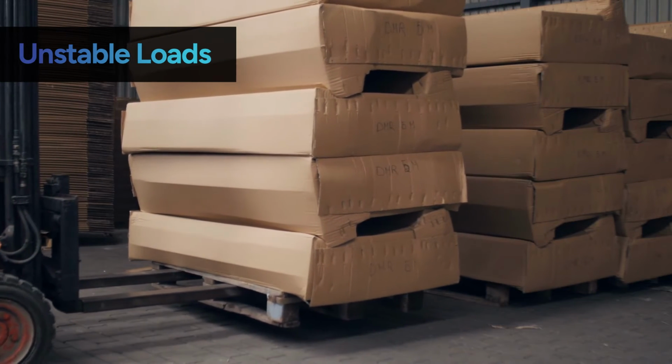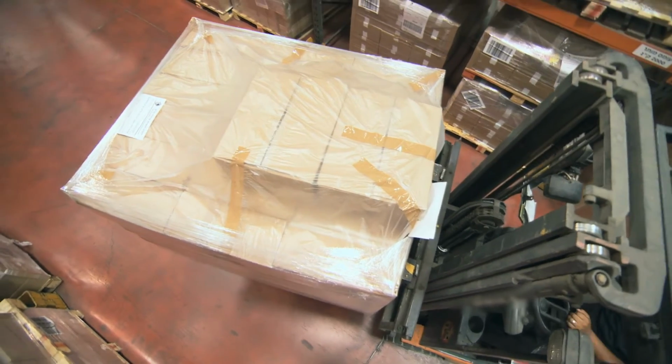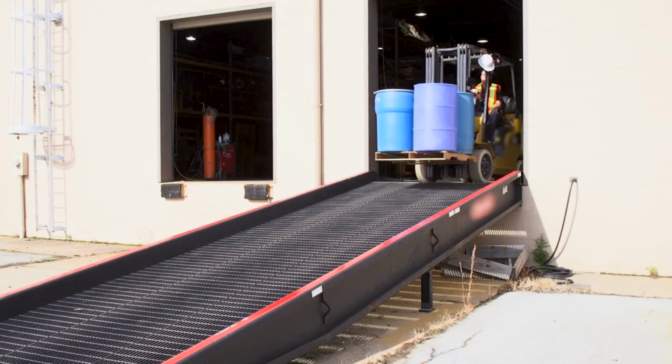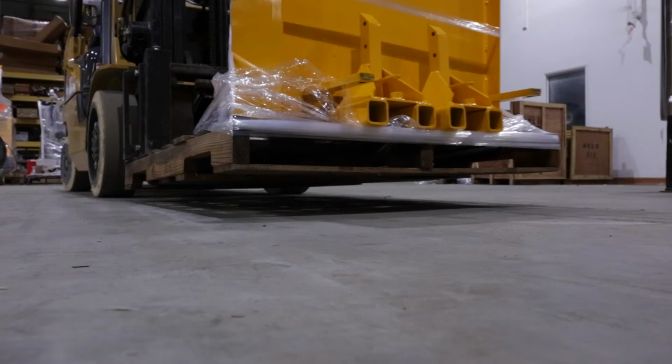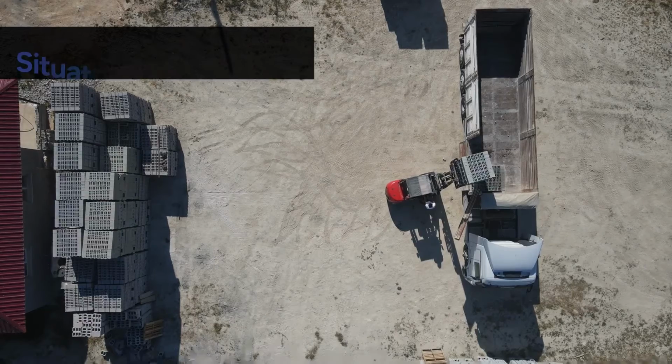Loose, damaged, or unstable loads can also impact the center of gravity. For example, if a load tilts or shifts during transport, it might move the center of gravity unexpectedly, leading to instability. Make sure all loads are properly secured, and exercise extra caution with loads that are loose, damaged, or inherently unstable. This vigilance helps to maintain stability and reduce the risk of accidents.